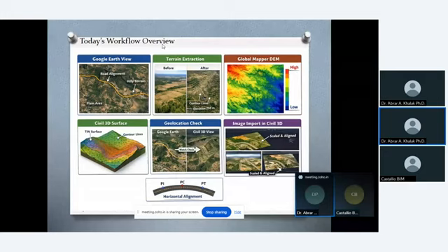Then geolocation check. Here we verify whether our imported data matches the real world location or not. The left side view is from Google Earth and the right side view is from Civil 3D. That is the fifth image. Then in number 6, image imported in Civil 3D. Here we import the image from Google Earth into Civil 3D, and then we scale and align it, which matches the visual exactly the same as the real world data.